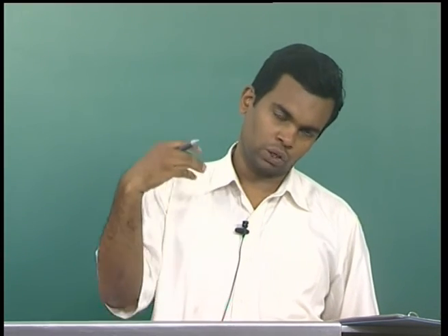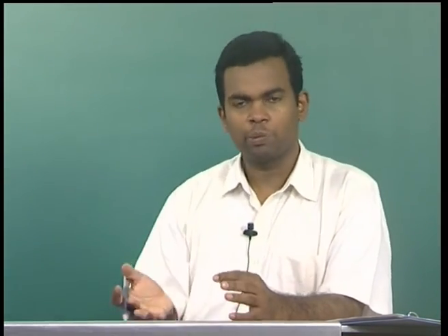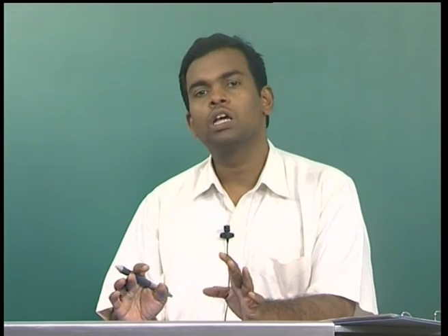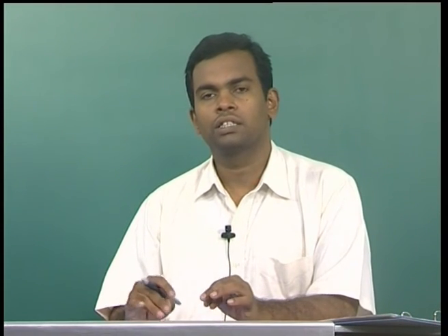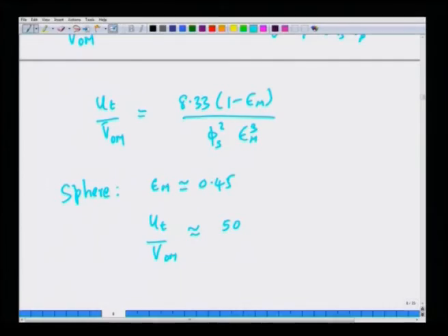Therefore, it is very unlikely for the particles to be entrained by the flow, because there is a very strong component of the terminal velocity which will tend to bring the particle down. Again, it will collide with other particles and go somewhat up, and it will also be pushed by the drag force of the fluid, but there is a very high chance that it will not go outside the bed. It will not be entrained.